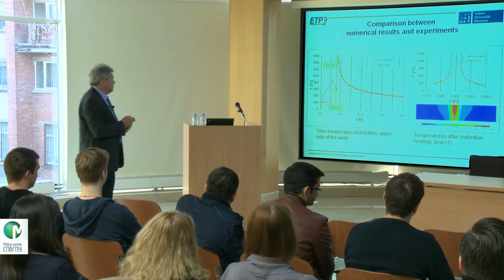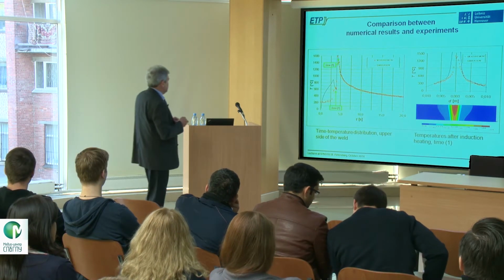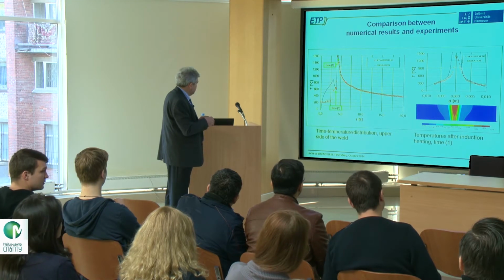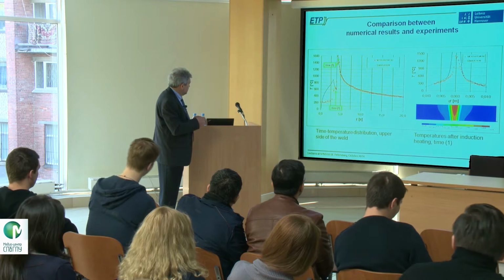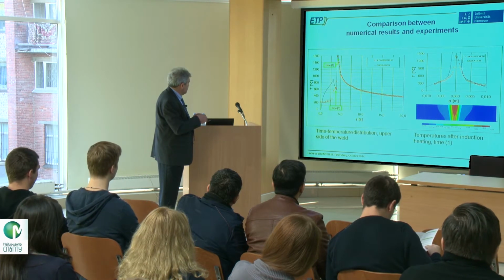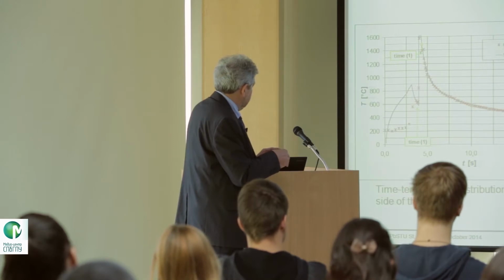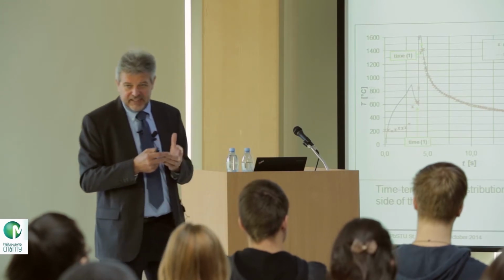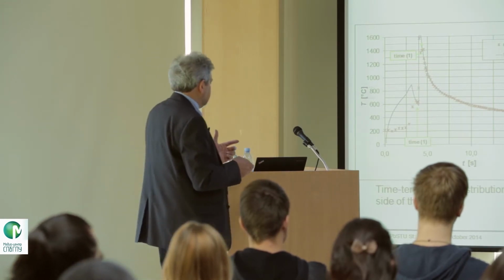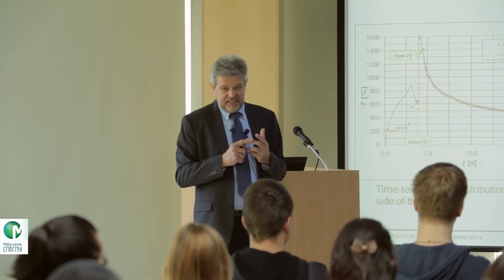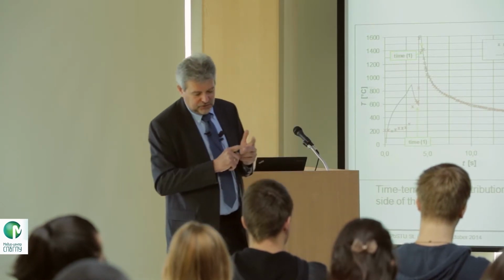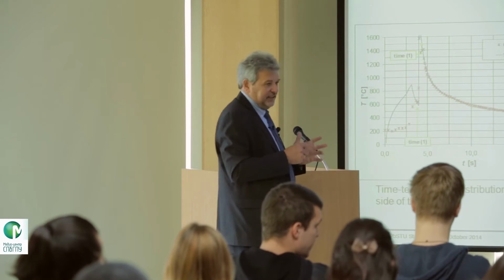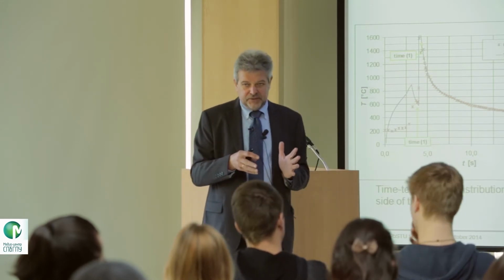And this cooling side is the important thing because the time between 800 degrees, you see here 800, and 500, this point here, 500, this is the critical cooling time. And if this cooling time is too short, then you have stresses and cracks finally. So the experts call it T85 time, 800 to 500, T8 time. And it means this T8 time has to be higher than the critical value.